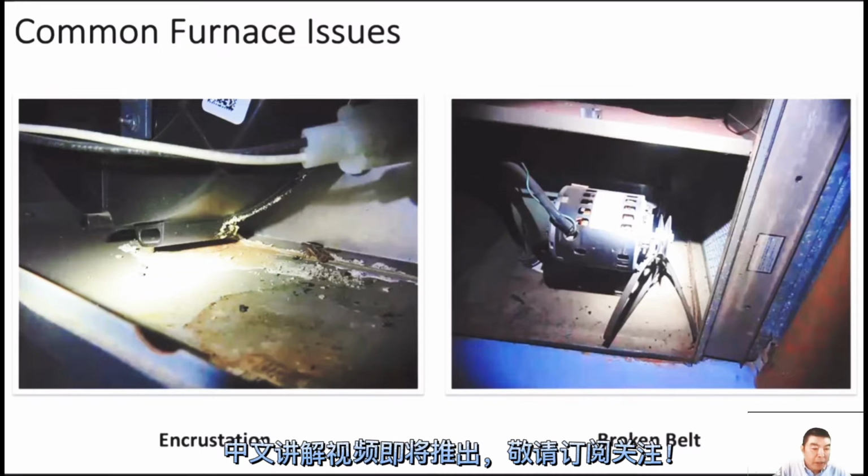If you see any stains there, it doesn't matter if the water is there or not, you should make notes and recommend doing the service. In the picture here, this must be category 1, because it's still belt drive. We can see the belt is broken already.